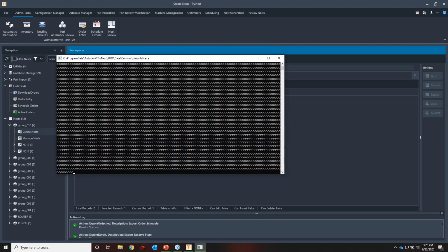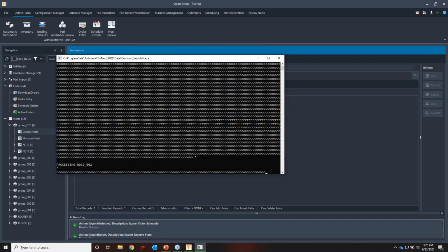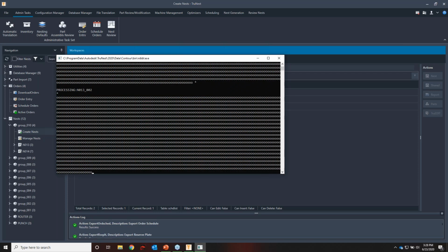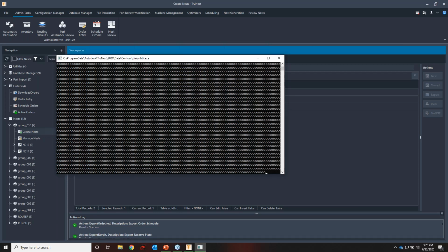So what this is doing is it's running an automatic tooling routine for both the internal and external contours on every part. And it's processing this based on the tool library that's currently set up in the system. So it's going to punch out each part on that sheet based on your current set of tools. Whatever rounds, rectangles, squares, special tools that you have in the library, we'll try to optimally use those on the parts that we've currently nested. So this allows you to essentially not have to tool all these yourself. It'll go through and do the tooling process automatically for you.